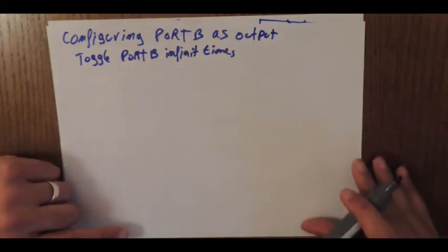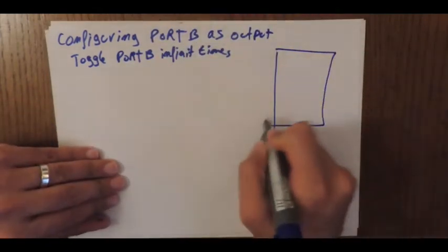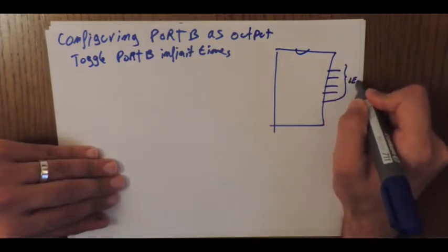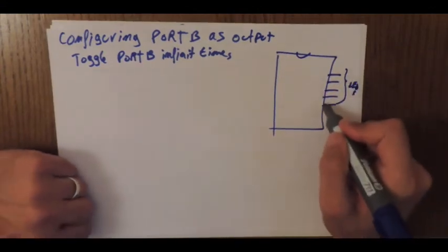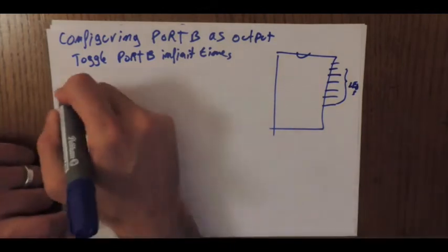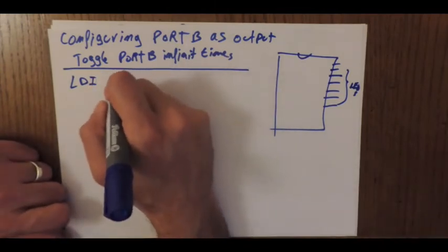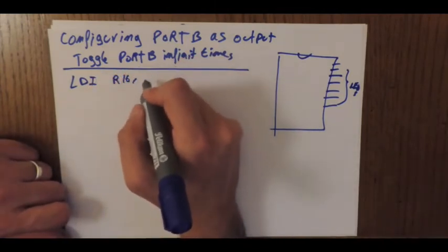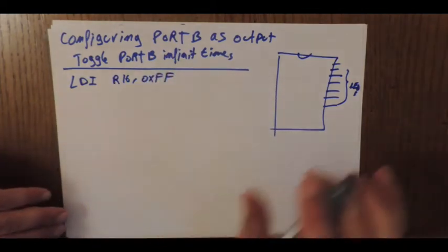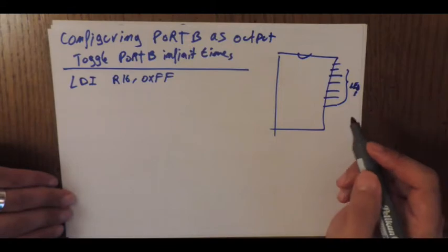So what we have here, let's say, imagine we have some LEDs, and this is the microcontroller. We have some LEDs on all the pins, and you want to toggle them. So first of all, I'm gonna place some value on port B. So initially, whenever we're dealing with problems that deal with I/O, we need to configure what we have here.